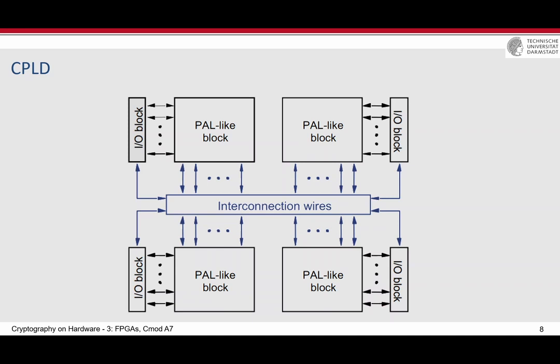And then, of course, this cannot be done manually. There were tools. The companies who produced CPLDs also delivered some tools and programs to realize this functionality. It means that you write your program again, like in VHDL or Verilog. I mean, at that time, I don't really know whether it was possible or supported. But anyway, by some description, you represent the function that you want to realize, and then the tool turned it into the configuration of the particular CPLD to realize this functionality.